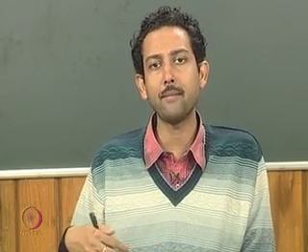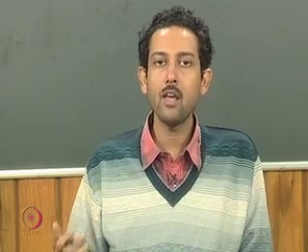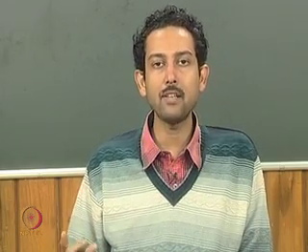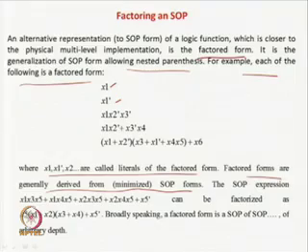That is, given a Boolean function in any arbitrary way, you have to first obtain the minimized SOP form, that is, you may minimize the 2-level implemented form, and from the 2-level minimized form, you can again factorize it to the maximal level, so that it becomes a minimized multiple level implementation format. So that is why 2-level implementation till date has a very great role in minimization of circuit implementation. Okay. So that is why factored forms are derived from minimized SOP forms. Minimized SOP forms can only be derived if you are using 2-level minimization algorithms.